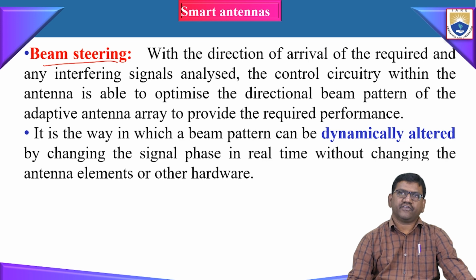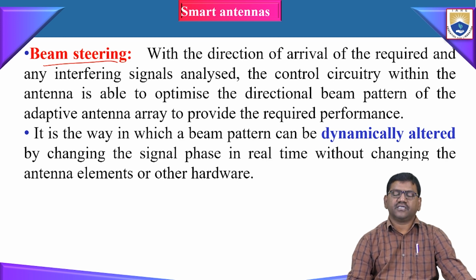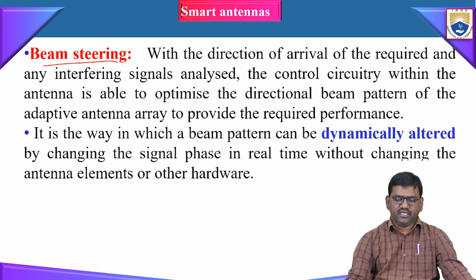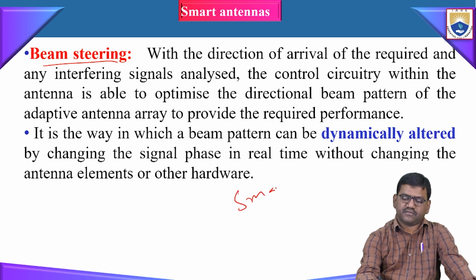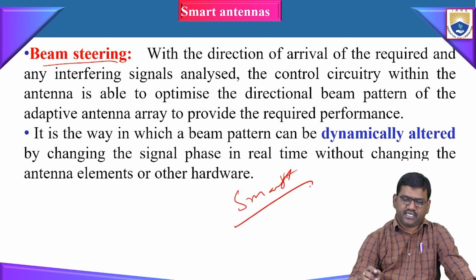Just the phase shift of the phase shifter attached to every element of the array, so the phase of the array will be changed automatically according to the signal environment. We need not add extra hardware or extra circuitry to the existing elements. So automatically the beam will be steered to the direction where the number of subscribers is more. Hence the name is given as smart antenna.